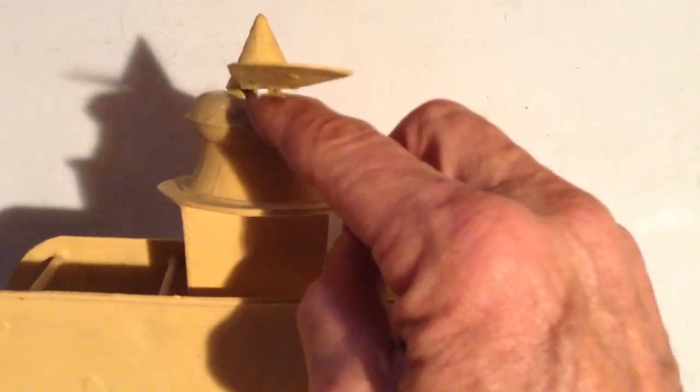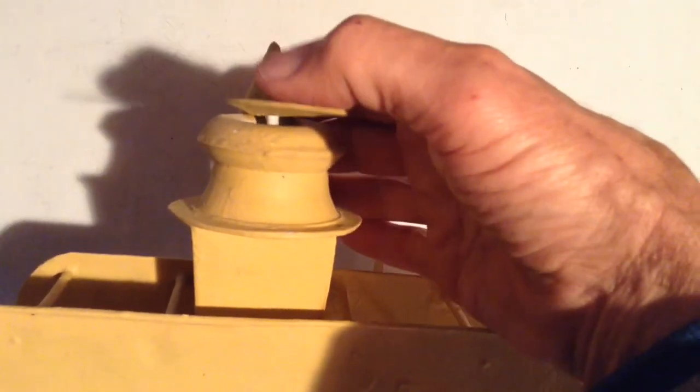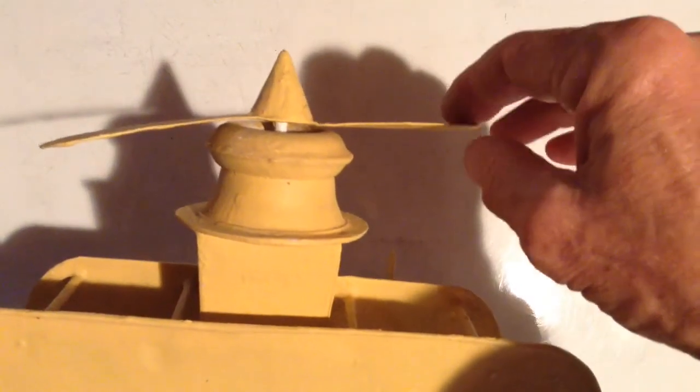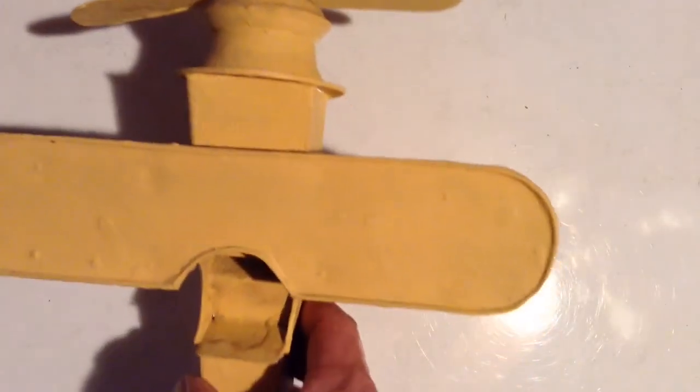Okay, I'm pushing forward here because I'm pitching it up. The propeller shaft is causing the plane of rotation to change. It's causing the top part to go backwards, the bottom part to go forward. But since this blade is going around this way, pushing on it while it's up here makes it go back when it's over here on the right side of the plane, which makes the airplane turn to the right.